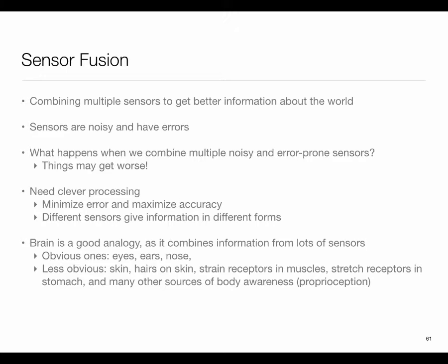Or for example, go to the problem of intruder at home, burglar at home. Motion sensor gives me part of the information, but we realize that it can be fooled. So we may combine it with information from, let's say, door and window sensors, and the two together can give me a more reliable estimate of what is happening. So sensor fusion is kind of the final part of the story, where we basically take readings from different sensors, which may even be located farther away, and combine them to reach my inference.